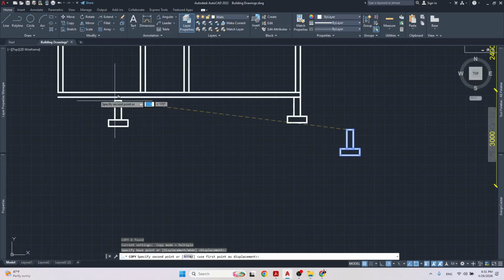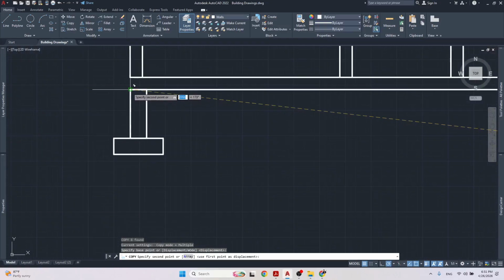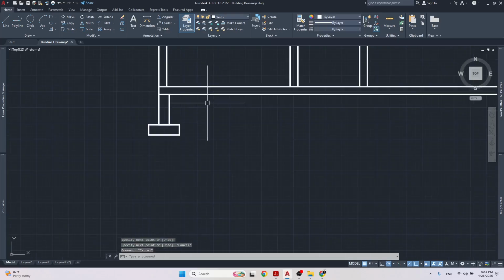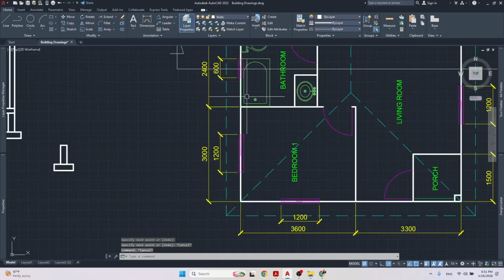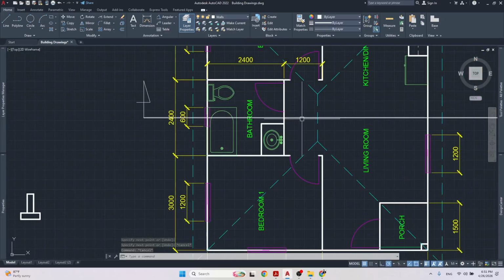for the other side. Now remember, underneath each load bearing wall there is supposed to be a footing. Okay, so there's going to be a footing underneath of this wall, there's going to be a footing underneath this wall, there'll be a footing underneath this wall. It actually would be all the way across here, although this wall stops here and continues there.